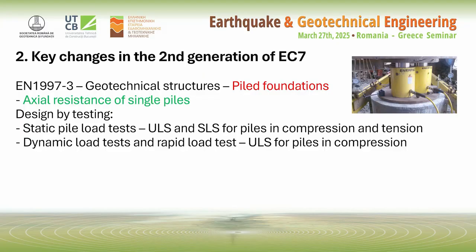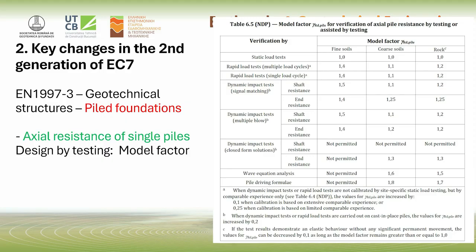We have also some considerations about design by testing. Static pile load tests are allowed for ULS and SLS in compression and tension, while the dynamic load test and the rapid load test only for ULS for piles in compression. Again, there is a model factor for a single pile for design by testing, depending on the different type of testing. And if it is a static load test, the coefficient will be 1, while if we are using a less reliable method, the value will increase.